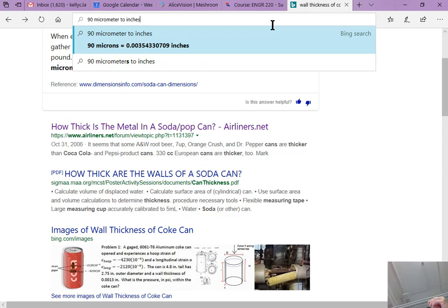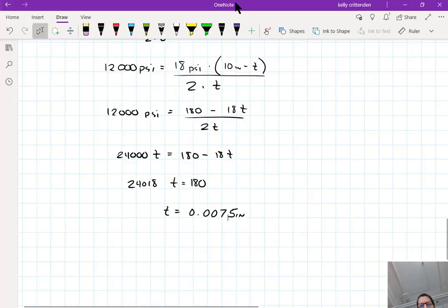And so I think there's more coloring, like paint on the can, than there is metal, or in the same range as much. So some of these pressure vessels can be super thin like this, but it doesn't say that that's the only thing that you'd have to worry about. Obviously, if these things have other stresses that you have to consider, then there would be other things. This only calculates being able to sustain the internal pressure.